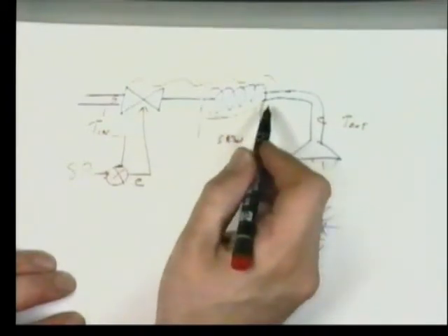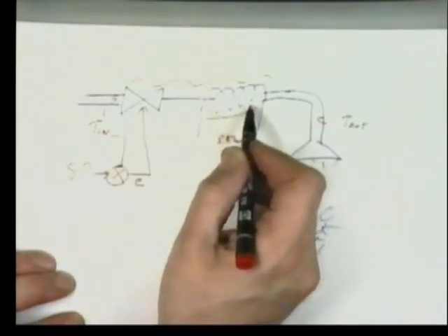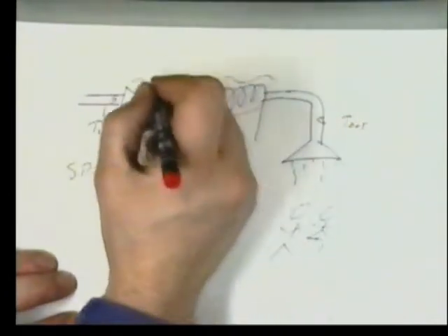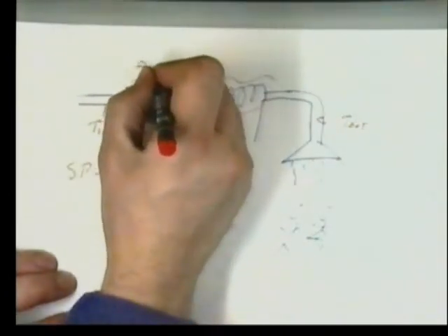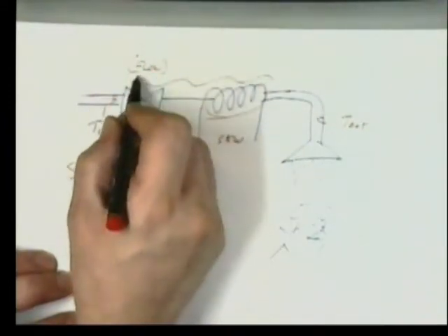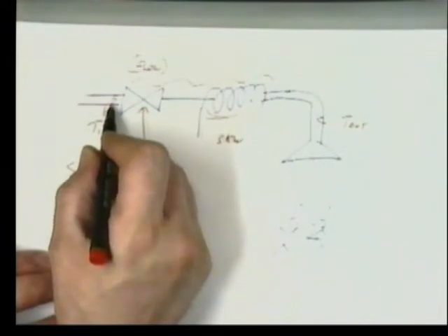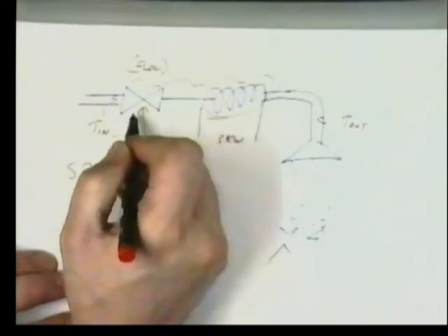So we know, because we know the specific heat of water, we know how much the temperature will be lifted based upon a particular flow rate. We can calculate the desired flow rate to raise the input temperature to the desired set point and adjust the valve. What we're trying to do is to predict what happens.